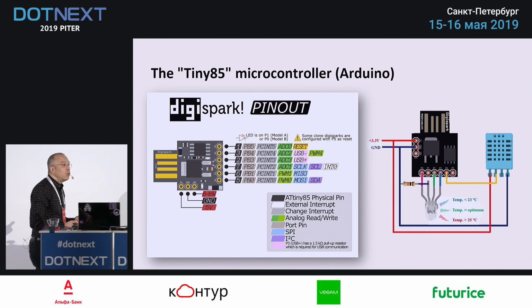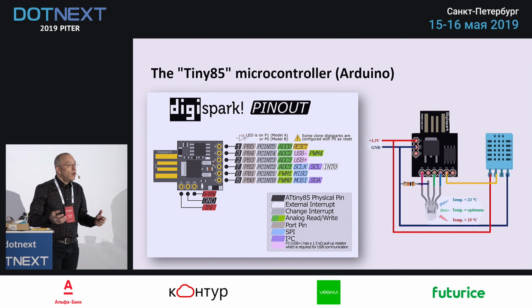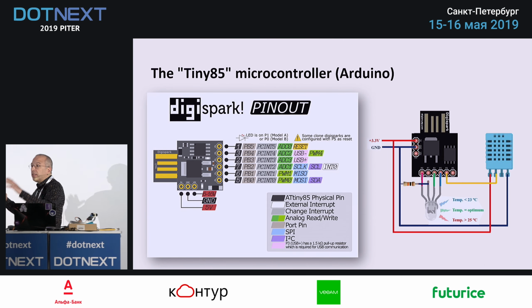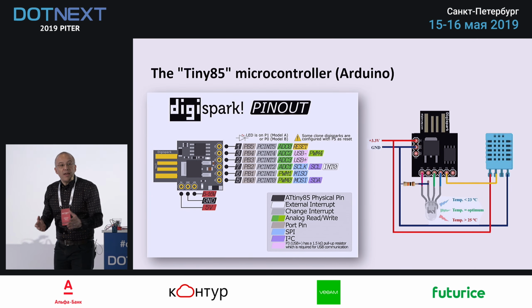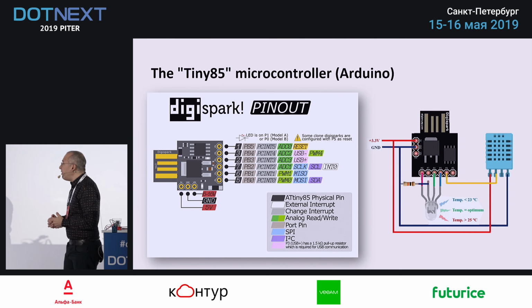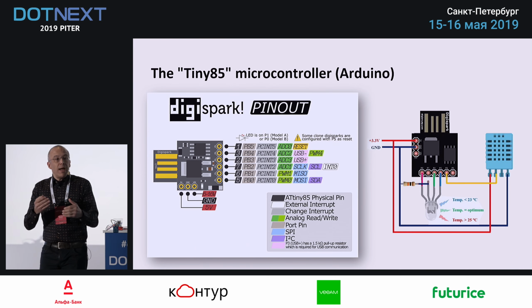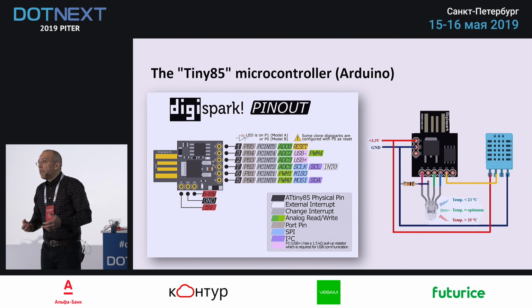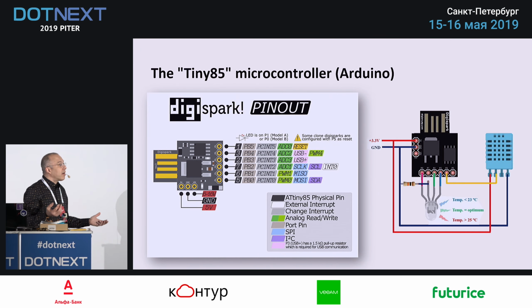And when you come to an operating system, you have a problem. You have multitasking, you have multi-threading, you are being interrupted even if you don't want. Even if you take your thread and you say, I am priority 0, I want to run with the priority that is best on my machine, you cannot have precise timing, and so it's extremely difficult to make the communication work with such a device. It's possible, definitely, but you may end up having some communication error you have to recover from, because from time to time, maybe the swap file comes. You have virtual memory, you have other interrupts that are coming.